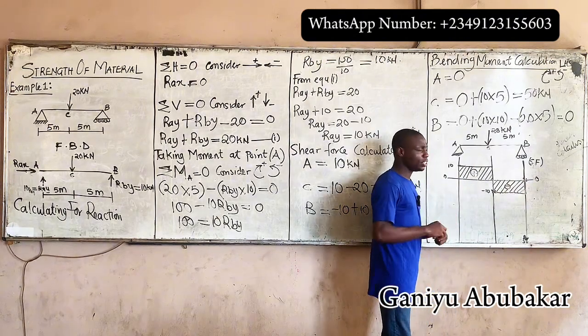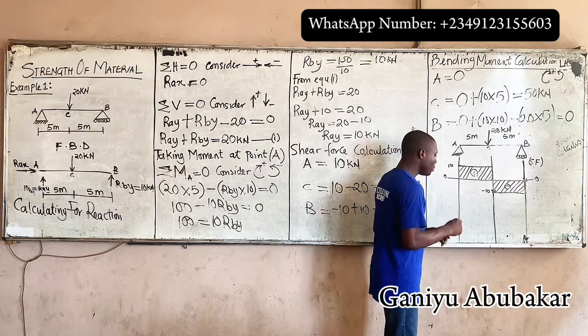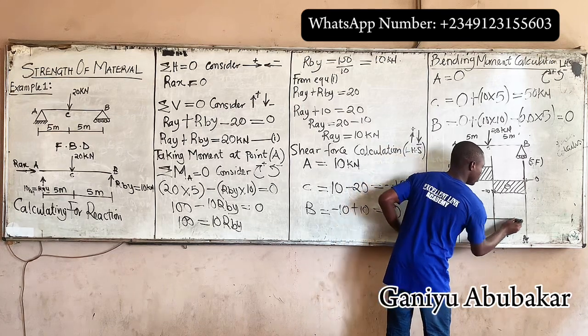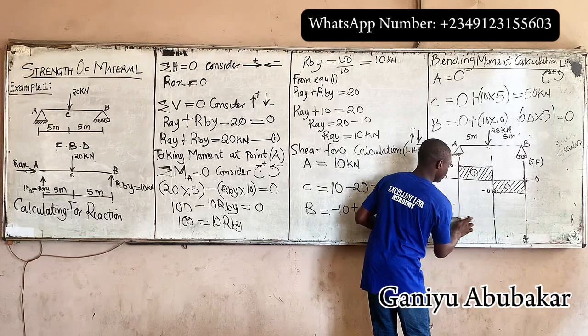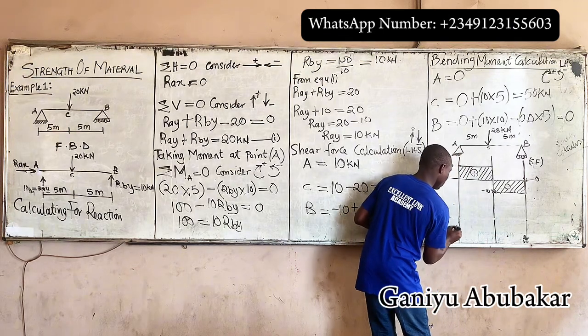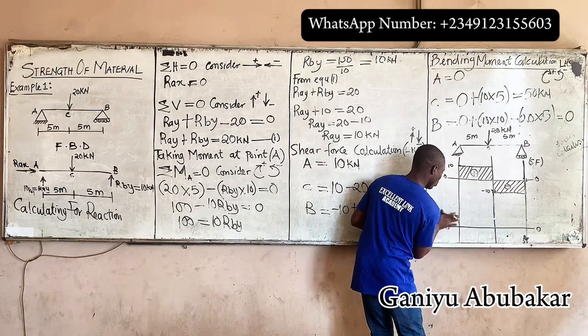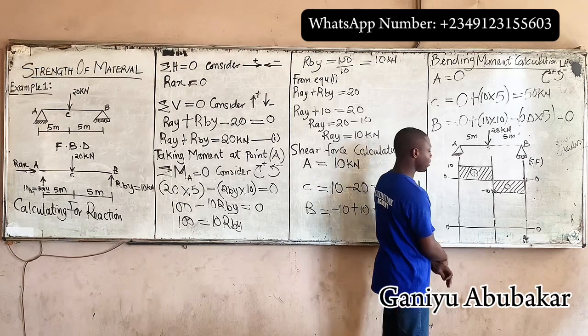Let's draw out the bending moment diagram for this question, okay? Similarly, I'll take a region of something of this nature. I'll take a region, call here point O and point O. So up becomes positive, down is negative, right?